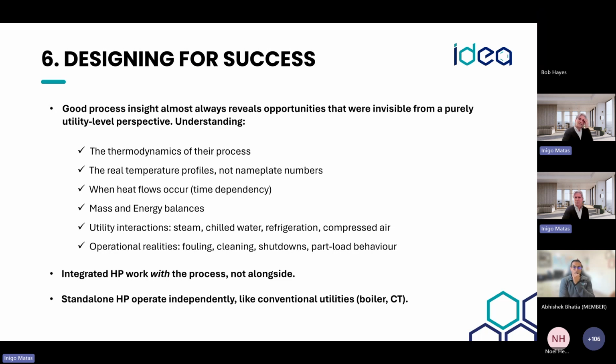Okay, designing for success. In the previous webinar, it was talked about how important it is to understand the process, especially when we are implementing these heat pumps. Having this good process insight highlights opportunities like the effluent, using the river, using air. All these are quite clear. But what we can get from the process, and this efficient way of using the energy within a process, is a bit more complicated, and that's where we can use what we were explaining before: understand the thermodynamics, make those mass and energy balances, understand very well the utility interaction, go very deep into the process basically.